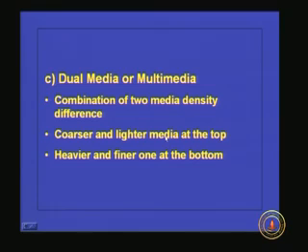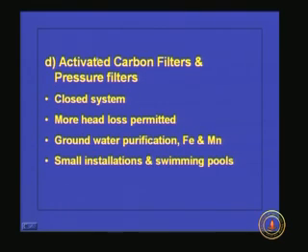If you go for a dual media filter, we can increase the filtration rate considerably compared to a rapid sand filter. Anyway, we will come back to the pore size distribution after discussing rapid sand filtration in detail. And another one is activated carbon filters and pressure filters.